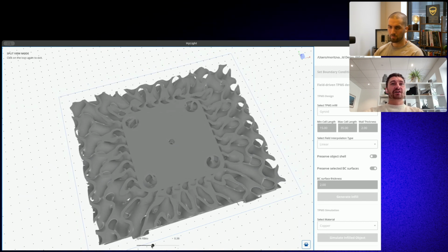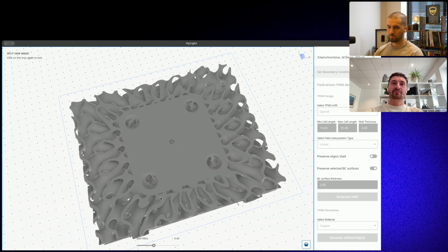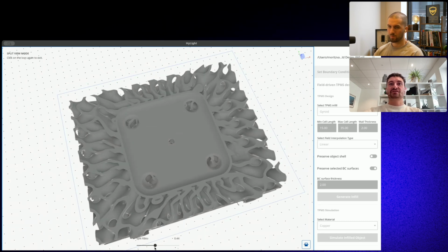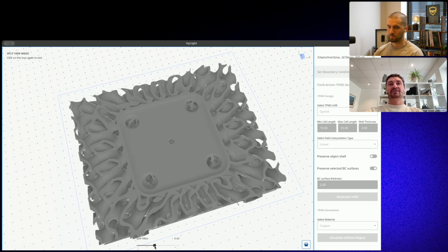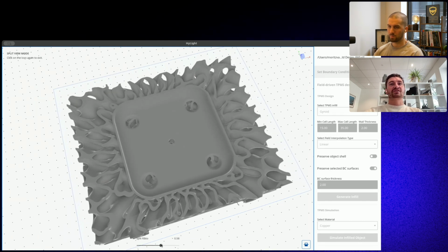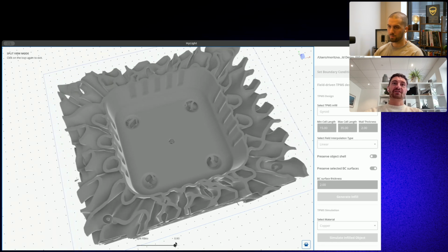And you can see that wherever the heat load is the highest, the gyroid structure is also the densest. So especially here in the kink of the mold, you would expect thermal stress concentrations. And here, in fact, the structure is also the densest. So this porous gyroid structure is here as dense as nowhere else in this mold.